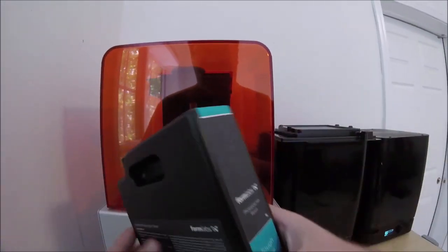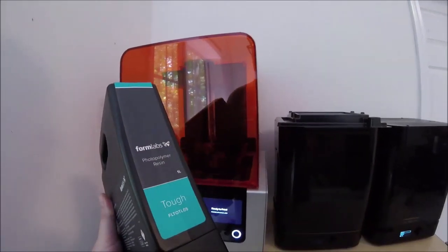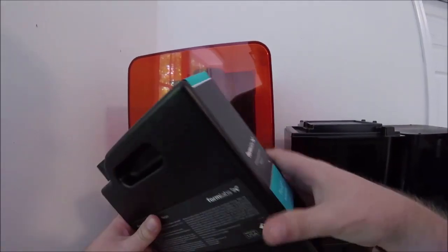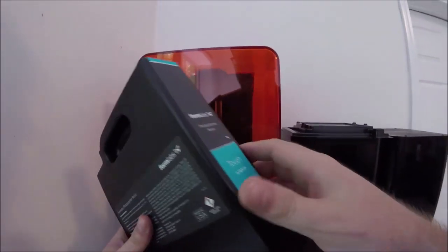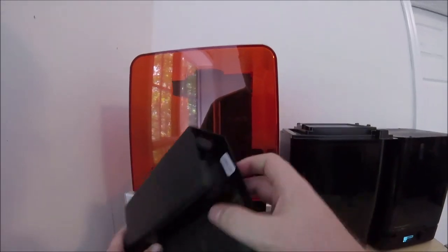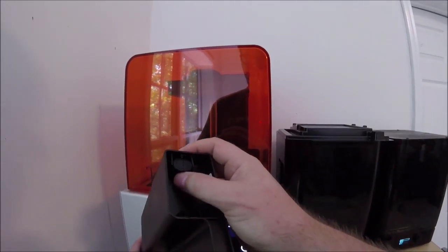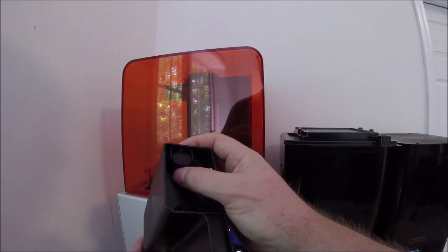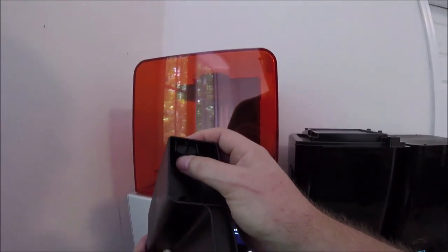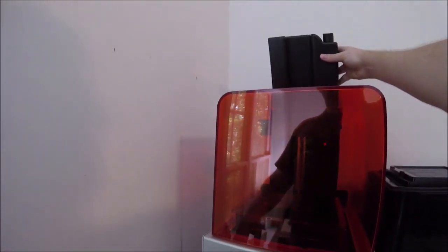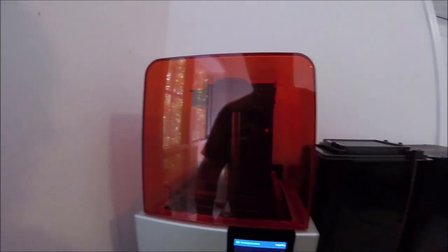We're done inside the machine, and we just need to install the resin cartridge. Remember, we're using tough V5 for this part. We selected that in PreForm. This is the cartridge. If you haven't shaken this already, you're going to want to shake this for up to 2 minutes. The other thing I like to do is check the bite valve here on the bottom and just make sure that it's opening properly. Sometimes they get stuck, and if you manually work this with your finger, you can ensure that's not going to happen once you put the cartridge in the printer. So just make sure that's opening up, and then go ahead and drop your resin cartridge into your printer and pop the air vent valve open.